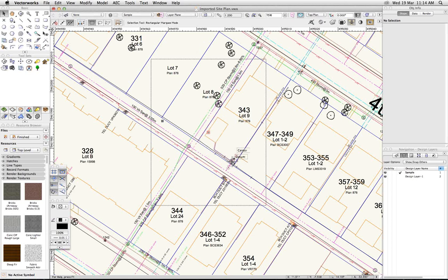So in my template, I'm going to make that adjustment. I'm going to move the adjustable user origin over to somewhere near those numbers. Okay, so I see 494980 and 5461980. You could jot those down, or you could make a point, copy and paste the X and Y values to the other file, however's easiest.